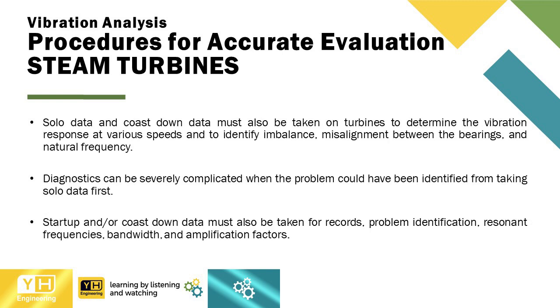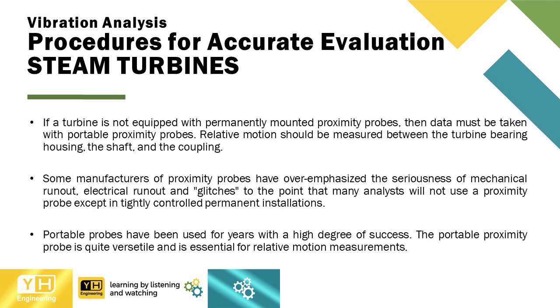Solo data and coast-down data must also be taken on turbines to determine the vibration response at various speeds and to identify imbalance, misalignment between the bearings, and natural frequency. Diagnostics can be severely complicated when the problem could have been identified from taking solo data first. Start-up and/or coast-down data must also be taken for records, problem identification, resonant frequencies, bandwidth, and amplification factors. If a turbine is not equipped with permanently mounted proximity probes, then data must be taken with portable proximity probes.